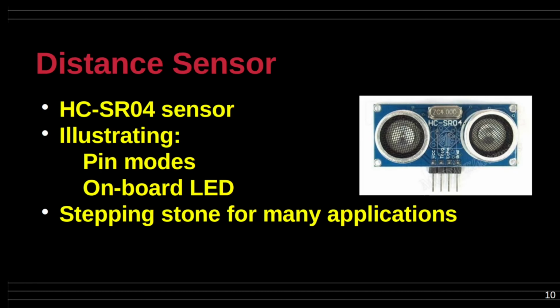We use a simple if-then-else clause to display the 3 different LED devices individually. Take a look at the code to understand how the mode for each of the applicable pins are set. 2 modes for the ultrasonic sensor, trigger and echo. 3 definitions for the RGB LED status devices.